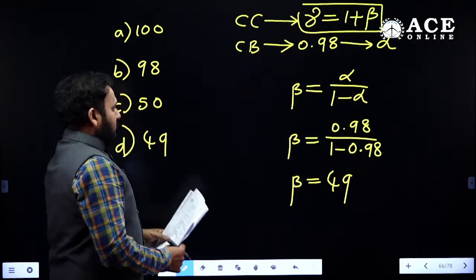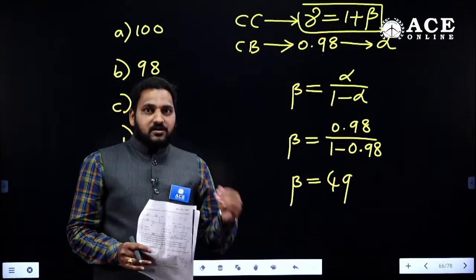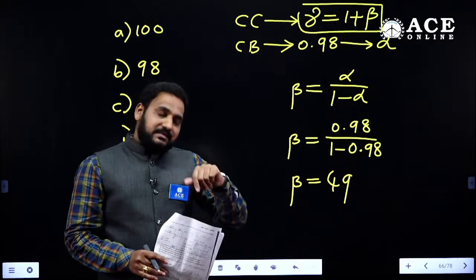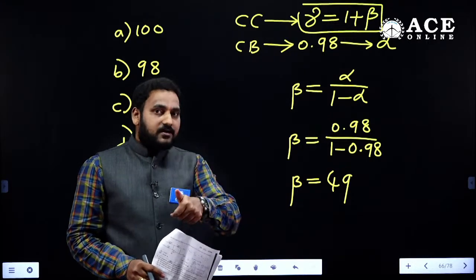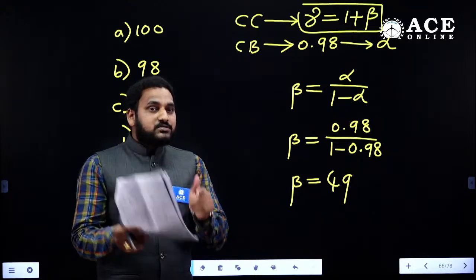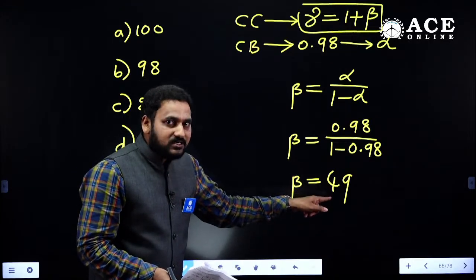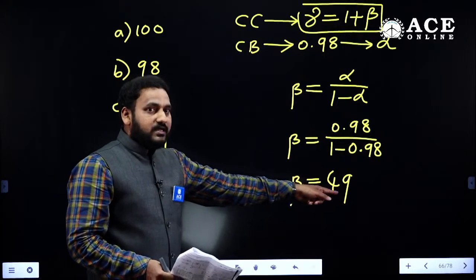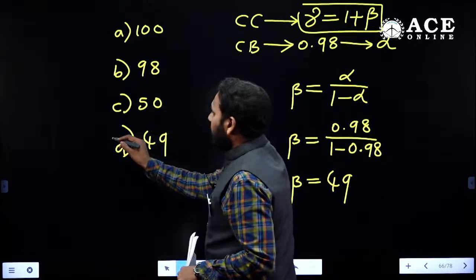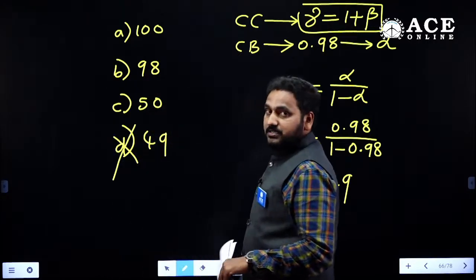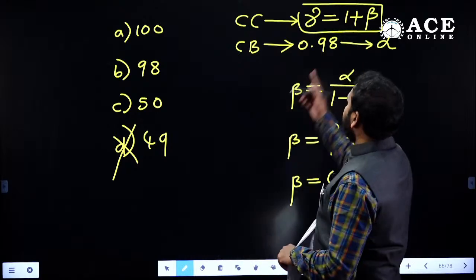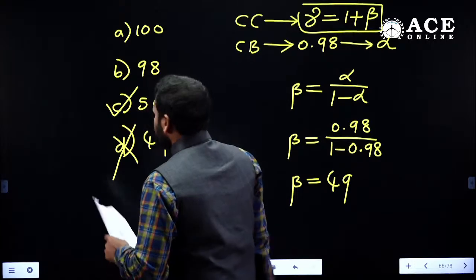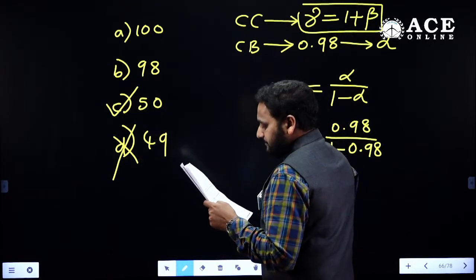I don't know whether you people could remember these things from the classroom notes or not. We have done this type of question with the help of a PNP type transistor. In that case also the question was given for beta, and I made the students select the value. Of course it is a wrong answer. Later I made the students realize that while doing the calculation you will get 49, that is the beta value. Do not immediately go for the selection of option D, because your target is not beta, your target is what? 1 plus beta. The question is given about gamma. So that answer is 50, option C.